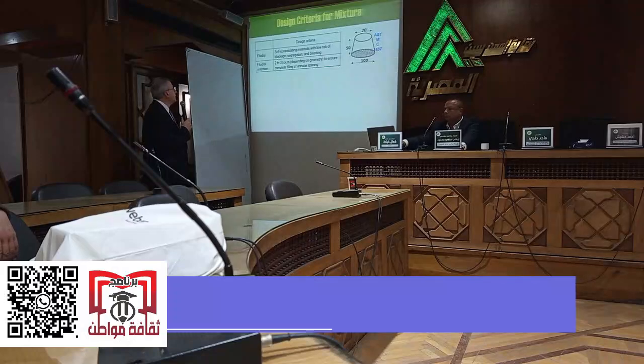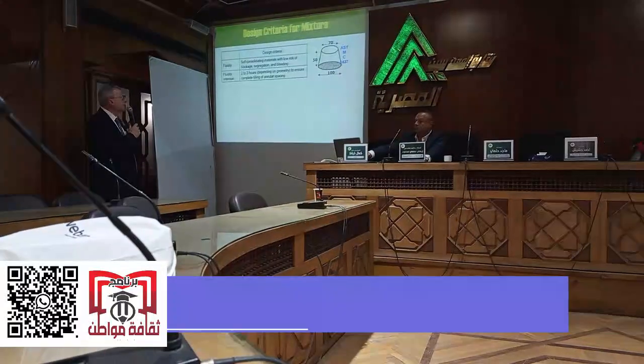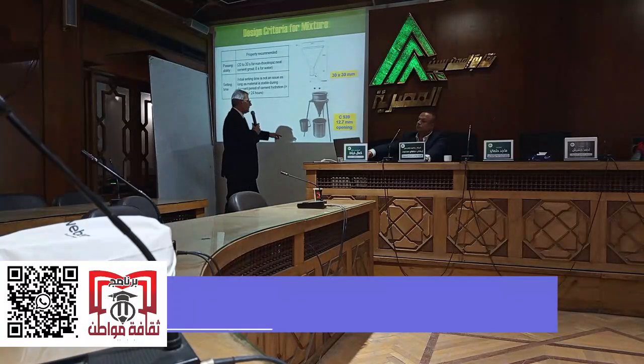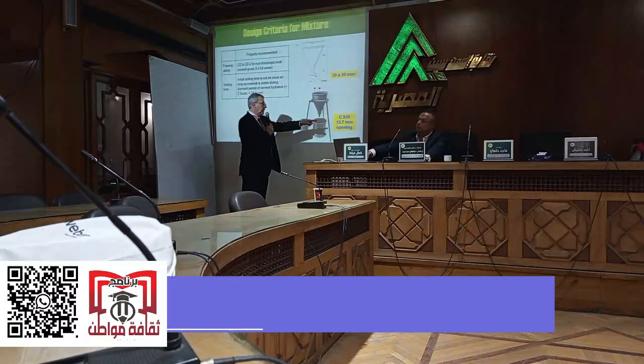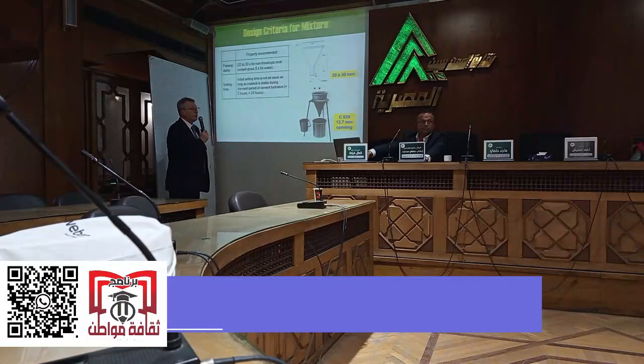Next. So a very simple test method, the slump, the mini slump. So this is not a slump cone, it's a mini slump. You have the dimensions. Next. We also did the passing ability using either the standard ASTM test C939. The opening here is 12.5 millimeter. You measure the flow time. Or a larger one for mortars, the V-funnel.